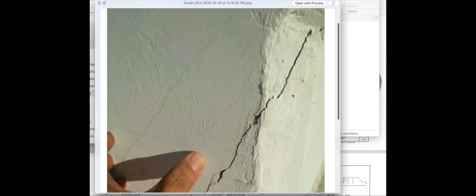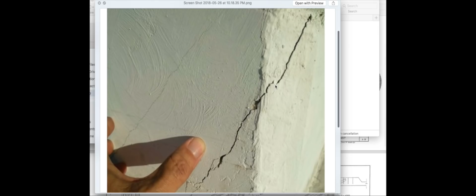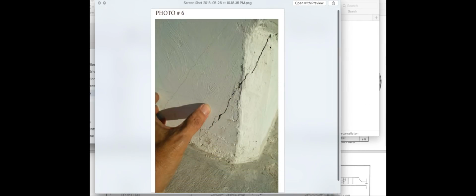And the pulling downwards, typically a bridge will deflect, the top and bottom cords will deflect in unison. This did not, but I'm saying we don't have a compression. We have separation, and as he said, tensile forces. So now we have the forms are not present at this point, which they're supposed to be during this post-tensioning. They were not scheduled to be removed until the bridge was in place.